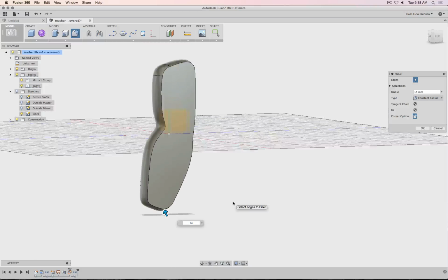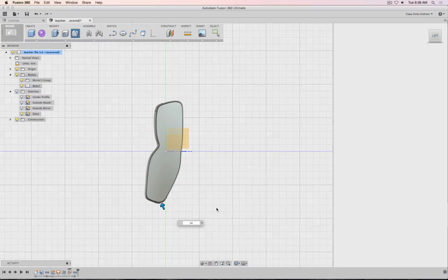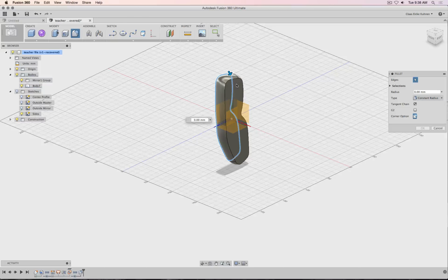And let's give it a moment. Ah, perfect. So you see this way we have those sharp edges just filleted, and then in a second pass, not path, I can actually fillet those other edges, those. And this one with G2, not G1, maybe 2 millimeters of a distance. Or 3, let's see what we can do.